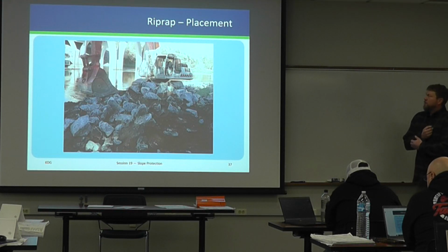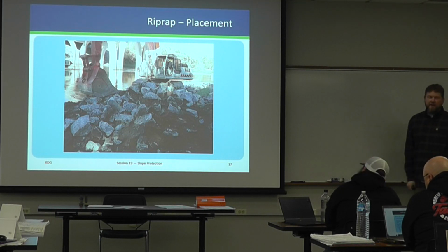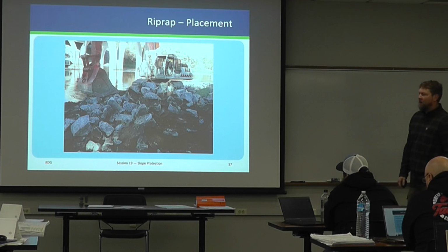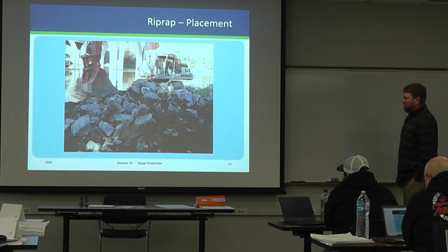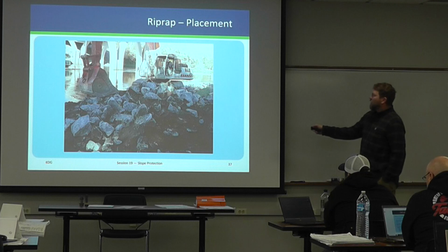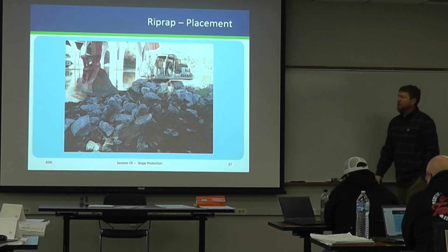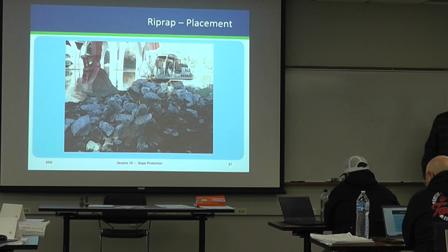Okay, so based on what we've talked about, does anyone have any concerns? If you walked up to this as an inspector, what would you be thinking? River's not protected. Now, I don't see anything along the river there. I would agree. Where's the filter material? Yep. Now, this one could be that they already had some placed, right, and it's underneath there, so it could be. But yep, you want to lower your filter. Is anything very dirty? Dirty.